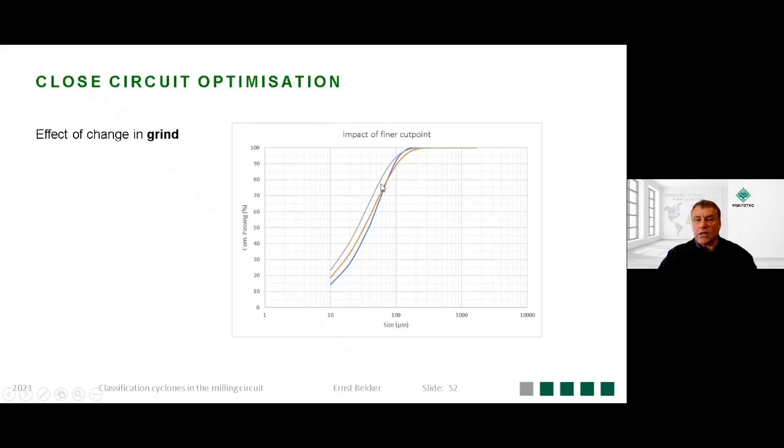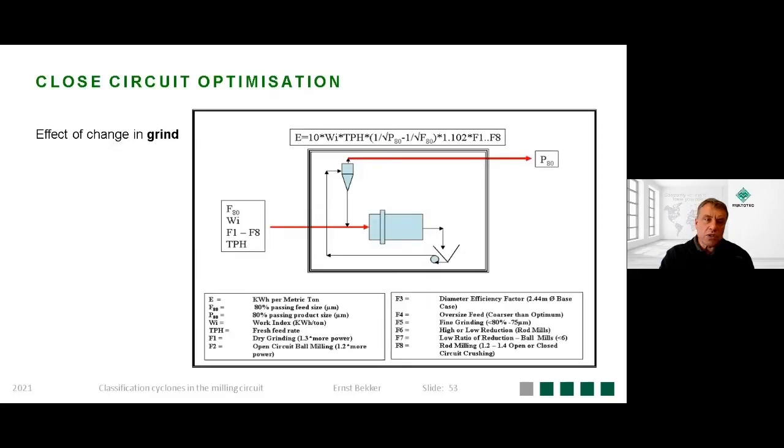But we're in a mill circuit, so we cannot make that change. And the more you think about the question, it's maybe not that they want to change the grind. They just want to minimize the amount of coarse misplaced material that is present. That comes back to looking at the feed conditions to a mill cyclone, so that we can see how far we can improve the amount of misplaced coarse material. Because, to reiterate, the cyclone does not control that PAT value. It's an energy-related mechanism.